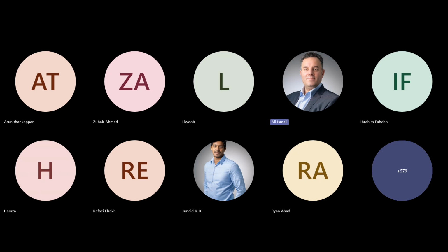This is for Umair. Do we need to submit DLTM coordinates in any BIM stage? I think this is the Dubai Local Transverse Mercator. I'm not sure, I'm not a GIS expert, but I think the BIM model should be geolocated. This means the coordinates of any point in the BIM model should have the correct GIS coordinates.